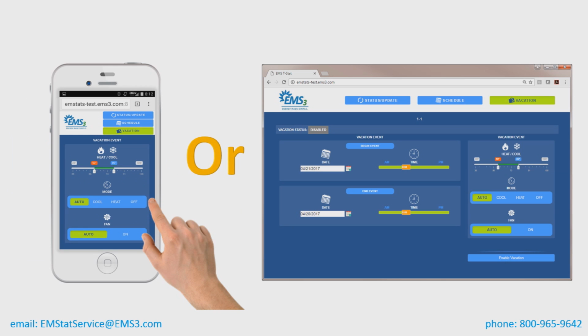Next, set your mode and fan to auto. These settings are discussed in more detail in the video for setting schedules, so I won't take any time here. Some people don't want their heat or AC to run at all while they're away. To do this, just set the mode to off and you can skip the next step. Keep in mind, though, that setting the vacation mode to off is not recommended during winter months where freezing pipes are a concern. Our recommended setting is auto.